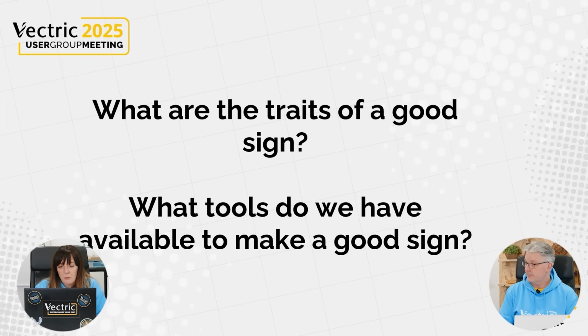The next thing I want to do is to create the stars that are going to go to the left and the right of the circle. I like the idea of that sheriff star. I think that would look really cool. So I'm going to go up to my layers, and I'm going to create a brand new layer, and I'm going to call this stars. I'm going to give this a color, green. That looks good. And then we will make sure that's selected, and we'll go back into our 3D view.